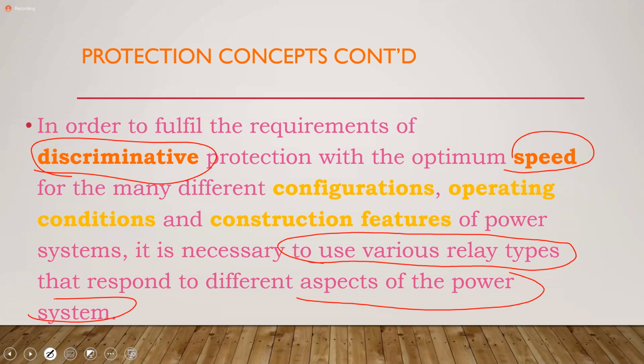But the fact is, once you have an issue, that relay would be able to detect it and provide you with some warning, or separate or shut down the generator, depending on what settings you would have made for it.